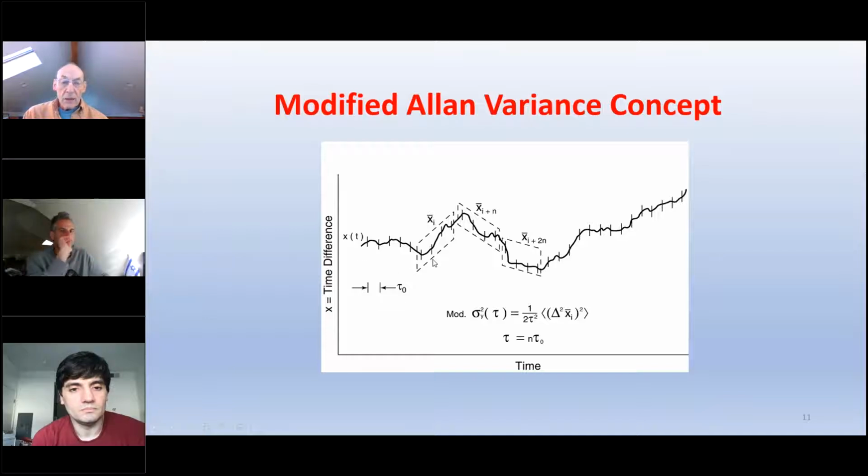Okay, and then the Allan deviation, this is the modified Allan variance, which is what I'm going to use mostly. But the Allan deviation originally is the change in frequency. You take the change in frequency over 2 neighboring intervals. How do you get the frequency of a clock? It's the offset in rate of a clock against the reference clock.